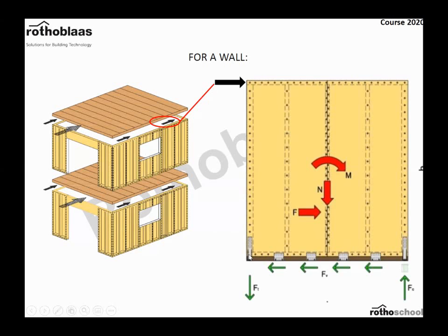And at this point, you're going to have a lifting force across this rotating moment force, and that is going to be stopped with also a long, narrow plate holding this corner down. And of course, this wind is driving the panel across. So these forces are resisted with these square angle brackets.